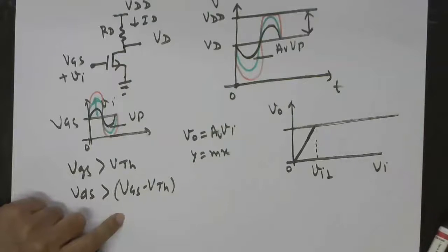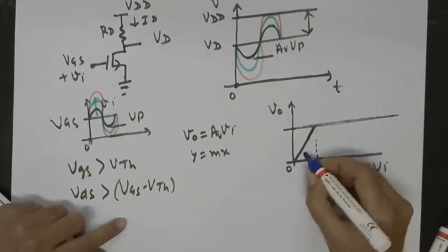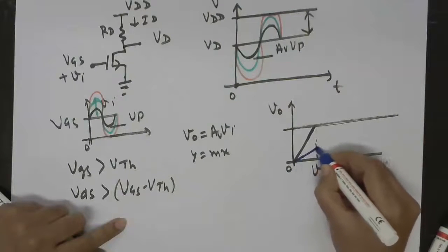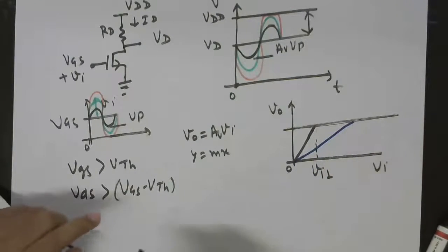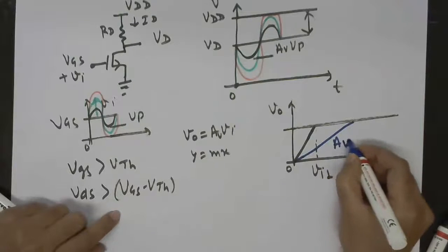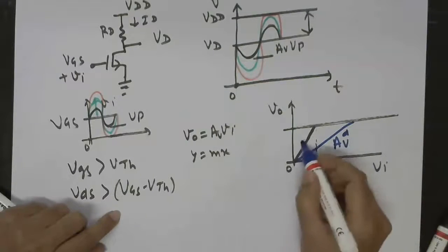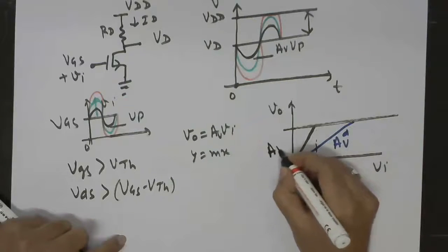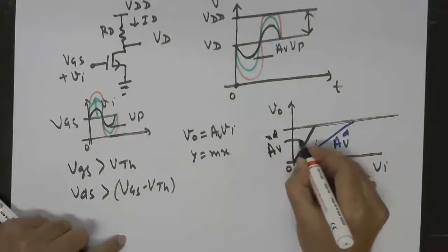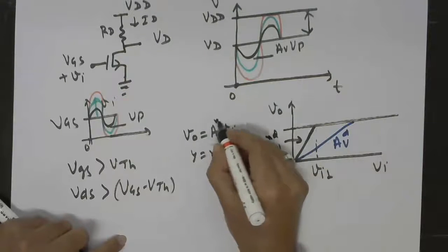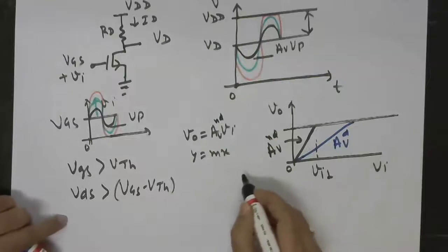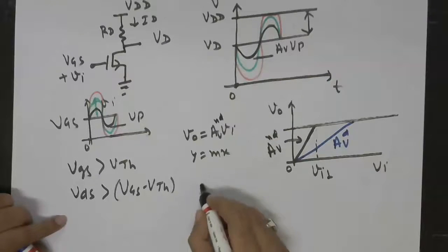What we can do is sacrifice the gain, and we can design an amplifier which has this kind of gain. So this will be AVD, and this previous one we will call AVND. So this is the gain for the ND case, the normal case, or actually non-degenerated.